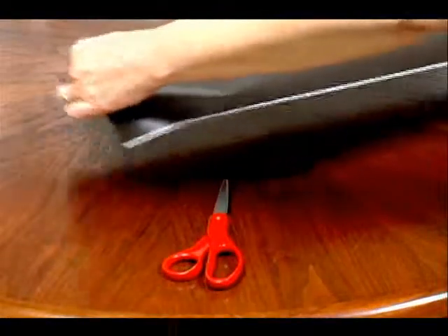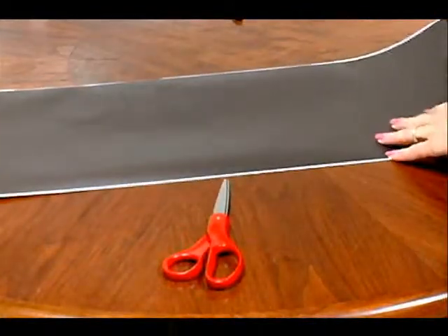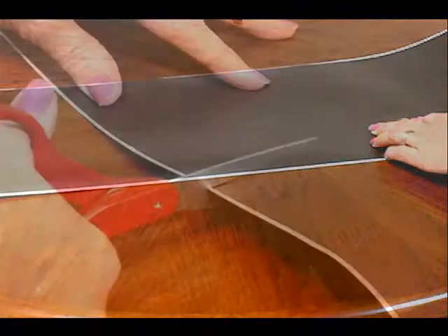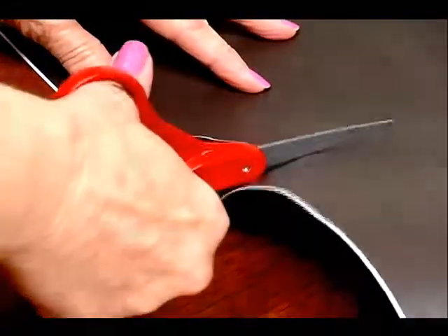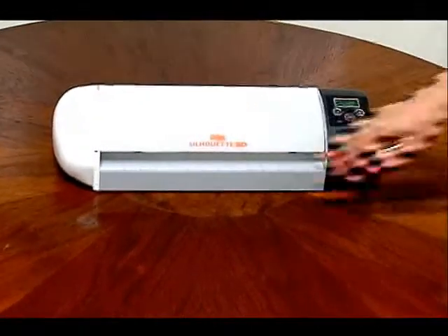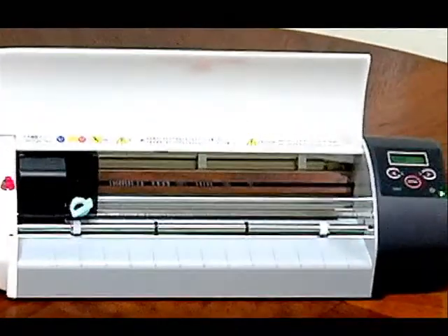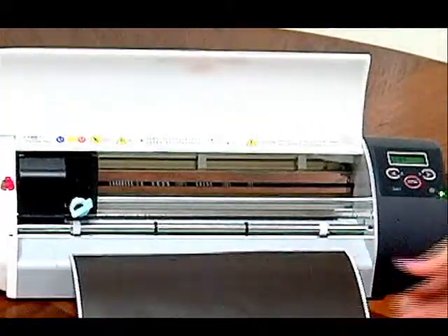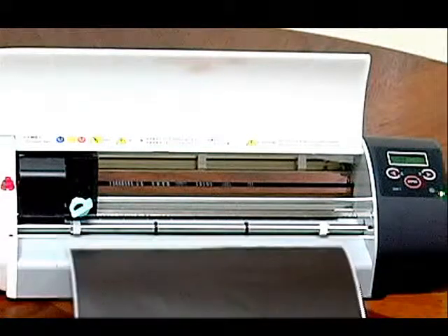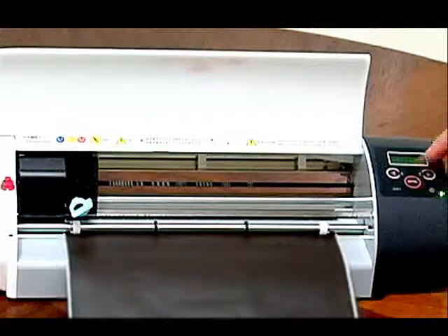Let's load the vinyl media. Since the design length is known, we can take our roll of vinyl and pull out the length to about the size of our cut area, which in this case is 18 inches. Once the sheet is cut, place an edge of the sheet on the writing panel evenly between the 2 white wheels of the silhouette. Press the Control Panel Enter key to load the sheet.